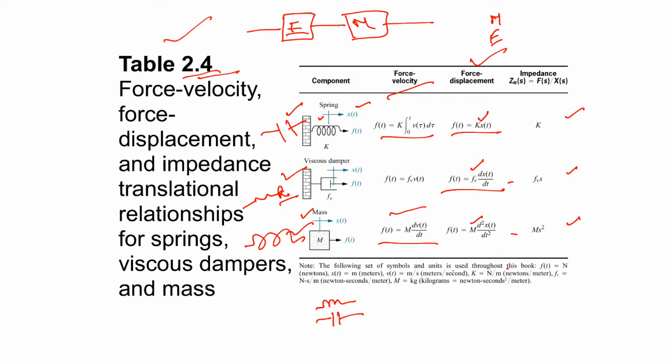Also, the spring in this case is analogous to inductor, which is opposite to the previous case, the viscous damper is analogous to resistor, and mass is analogous to capacitor. The summing forces written in terms of velocity, in this case, are analogous to summing currents written in terms of voltage, and the resulting mechanical differential equations are analogous to the nodal equations. In the further lecture we will discuss this.